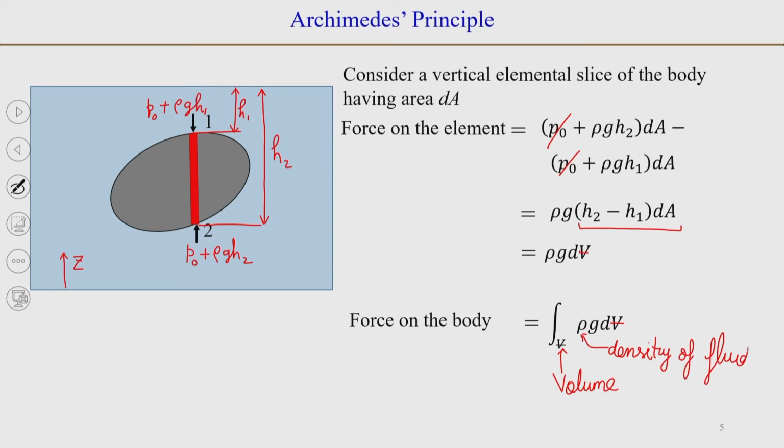So, again the force on the body is equal to the weight of the fluid that is equal to the volume of the body. So, again we have been able to derive Archimedes principle. Now, in hindsight we see that Archimedes principle is nothing but an extension of the principle of hydrostatics, that P is equal to rho g h at a particular depth h in a fluid.